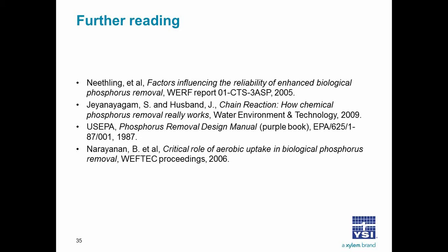As far as using them together, typically feed-forward control would be used also with some feedback control as a trim. Models are not perfect, as we know, and the feedback control would eliminate the errors in the model.